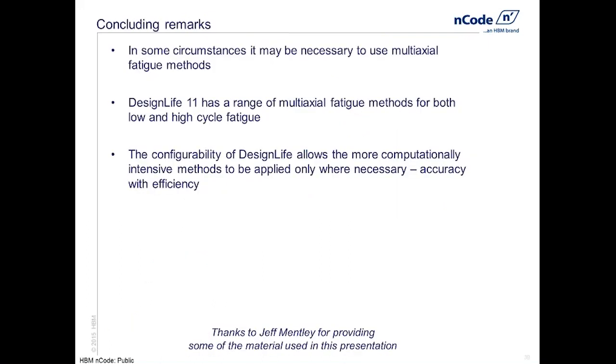Okay, so a few concluding remarks. It's not always necessary to use multi-axial fatigue methods. In some circumstances, it is. So in DesignLife 11, we've provided a range of multi-axial fatigue methods for both low and high cycle fatigue, for both proportional and non-proportional loadings.